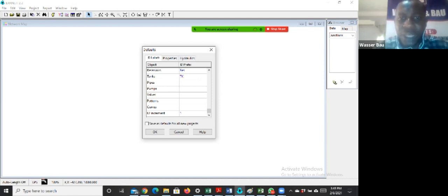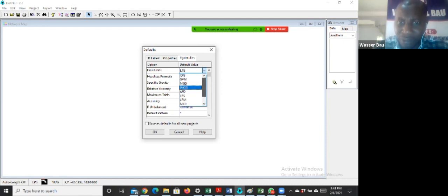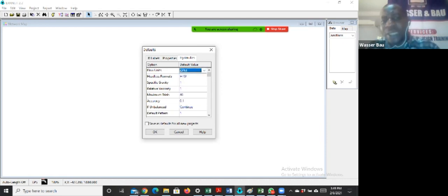The next thing I do is set my properties. I go to hydraulics and check the unit. I'm doing it in gallons per minute because that's the unit the tutorial came with. It's the American unit. The head loss formula, I'll leave it as 100. The maximum trial, I can leave at 0.1 or I can say 0.01. It just depends on what you want. If you input any value, you tap enter.